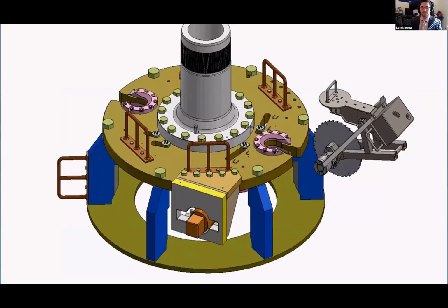Next, we did some shaft calculations. The critical speed calculation we did was 9,861 RPMs. We did this calculation to make sure that we weren't reaching the resonant frequency and our tool would fail. Next, we did our bearing life calculation, which we found to be 3,766 hours. We know that the tool can only be down there for 2 hours per Schlumberger's recommendation. So we know that the 3,766 hour life is plenty of time.